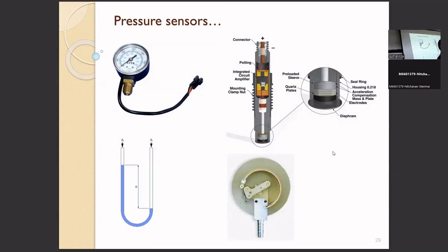Okay, that means if you read the pressure from equipment, you get the pressure past atmospheric pressure. That's atmospheric pressure, PATM. For example, you get the absolute pressure, and then you can calculate some value. You open the steam table, you open some property. This is also very important.